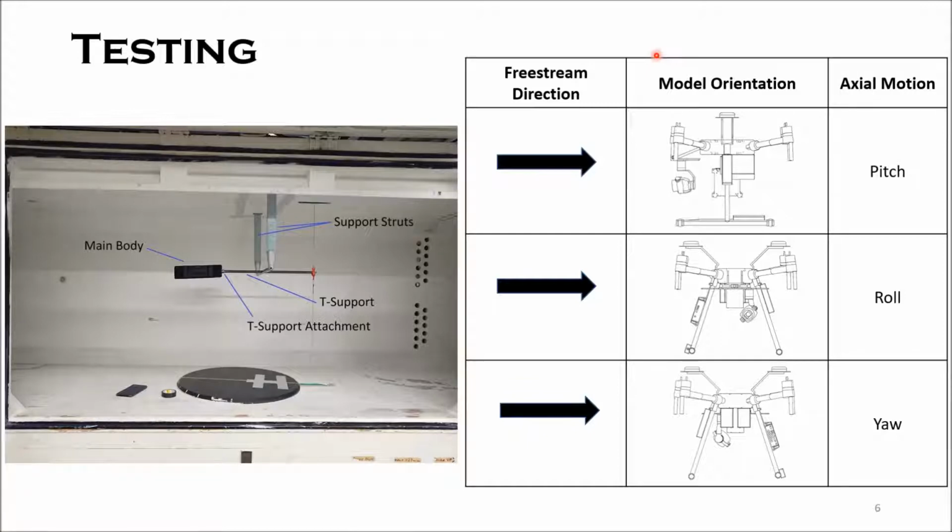Prior to testing, calibration of the load sensors, pressure transducer, and temperature sensor was carried out to ensure accurate and stable readings. The tare values of the sensors, or their initial increment if any, were recorded prior to each run so that they could be eliminated from the test data.